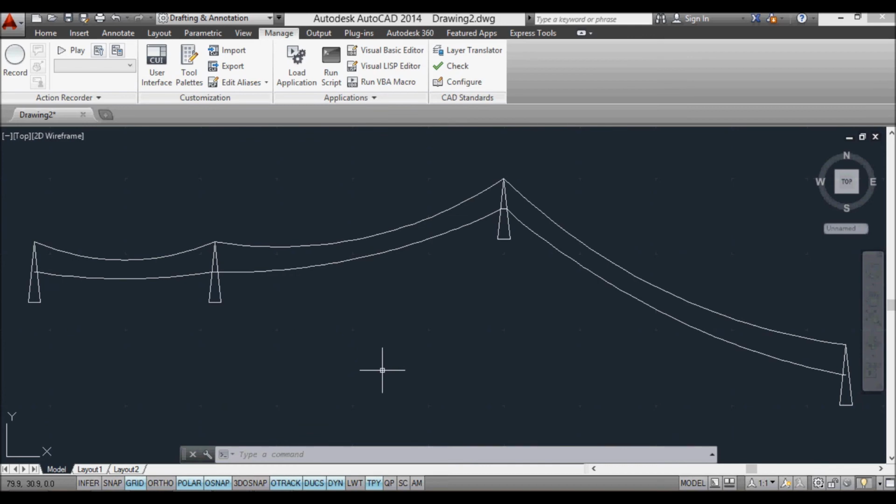Now you'll notice that the catenary curve is going to change massively depending upon the tension and the weight of the cable. Obviously the greater the weight, the more sag it's going to have towards the middle, and the greater the tension, the tighter it's going to appear, so the less sag towards the middle. There are lots of other things you can do if you want to get a real proper way of doing this, which takes into account lots of different things, including temperature, and the coefficient of expansion of the material you're using, the conductor. What I suggest you do is use software called SAG10. That's the industry standard software that's designed for doing this. All I've done with my routine is just basically done a little arc just to show you how it works.